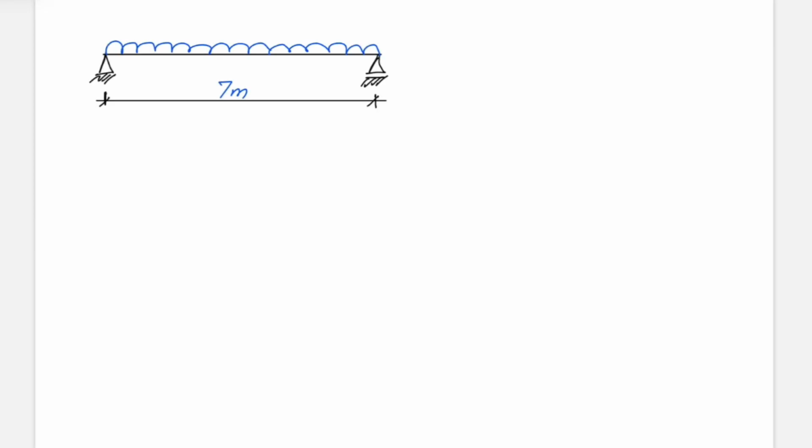This example shows that a 7-meter span with a 4-meter tributary width is technically possible but often expensive and impractical in residential construction. In typical residential floor conditions without intermediate supports, spans beyond about 5 to 6 meters usually require very deep beam or steel sections. Adding an intermediate support, such as a column at a kitchen island, can dramatically reduce beam size, deflection, cost, and installation difficulty. Structurally, this is often the most economical solution.